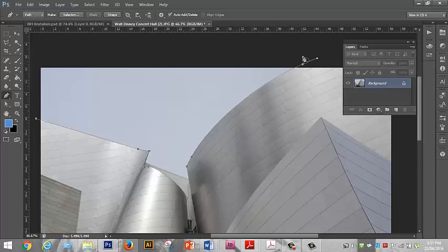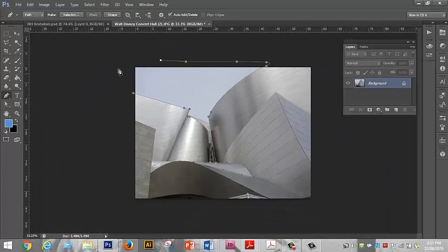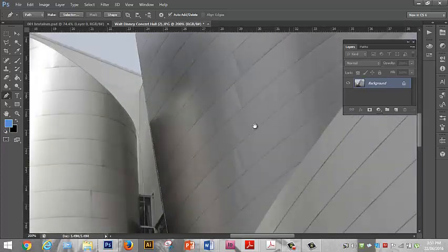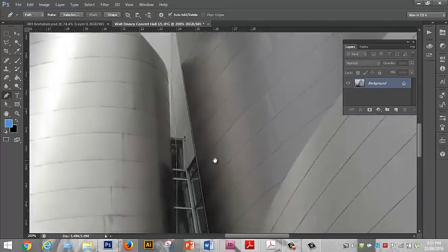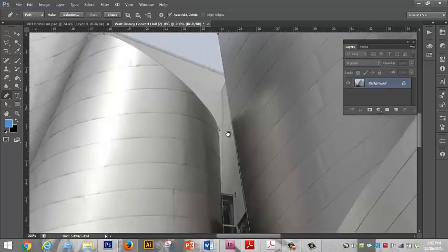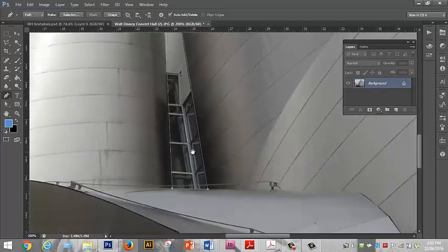There we go. Okay, so let's continue. And again, just as before, let's go all the way around and finish it off, meeting where we started. Now I'm going to zoom in and correct this little extra bow that's happening. So control changes back to the little white arrow, and I just need to push back one side of that anchor. That looks not bad, and maybe move that in a little bit.